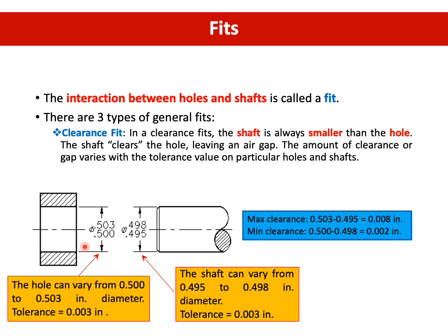You need to know that there are three types of general fits. First of all, you have a clearance fit, where the shaft is always smaller than the hole. That means there is not going to be any disturbance, your shaft can always get into your hole. So this is called your clearance fit.